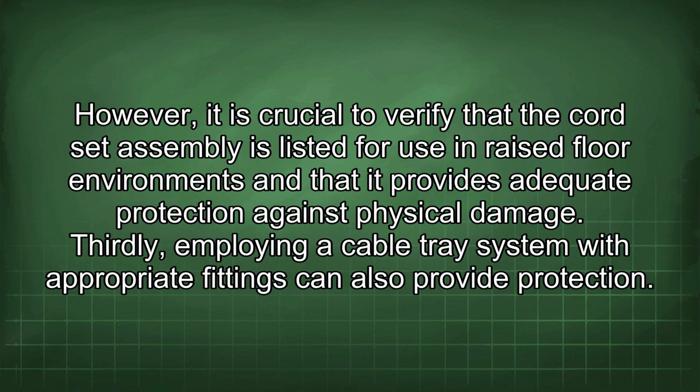However, it is crucial to verify that the cord set assembly is listed for use in raised floor environments and that it provides adequate protection against physical damage. Thirdly, employing a cable tray system with appropriate fittings can also provide protection.